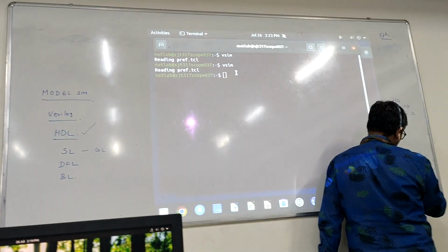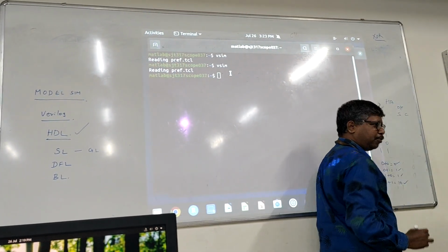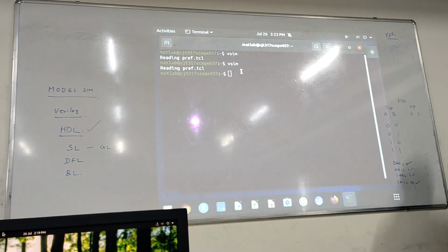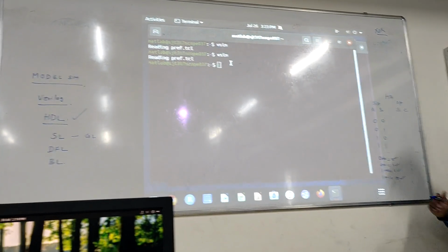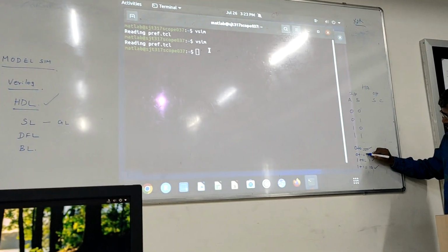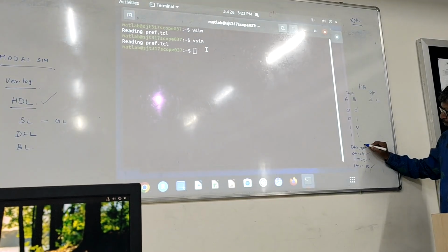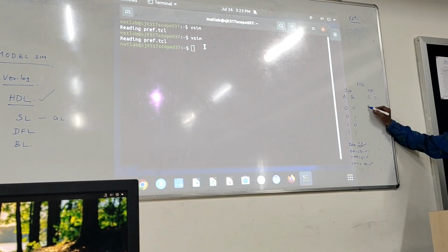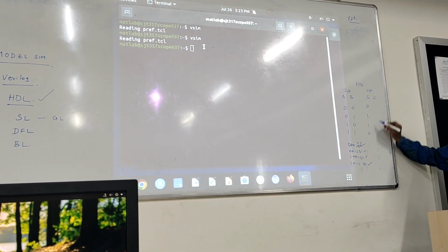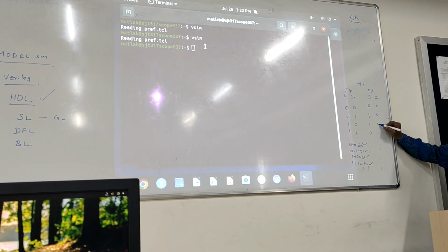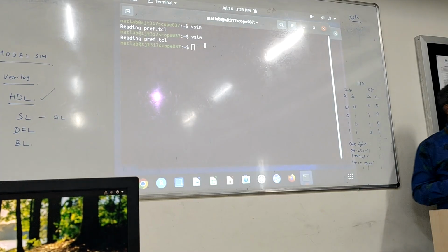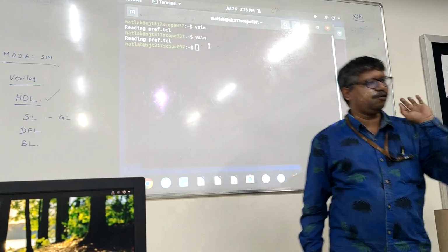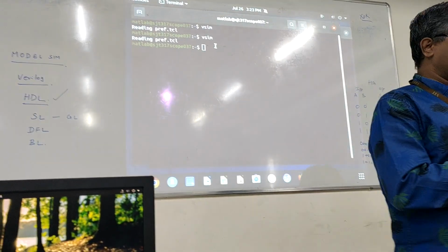Here you can see 1 bit, 1 bit, 1 bit, and a 2-bit output. So I am going to make all the output data the same size. I am going to pad a 0 before it, and I am going to name this bit as sum and this bit as carry. I am filling it here: 0, 1, 1, 0, 0, 0, 0, 1. Understood? Any doubt in the truth table? So using this truth table, I can define the functionality. One method.